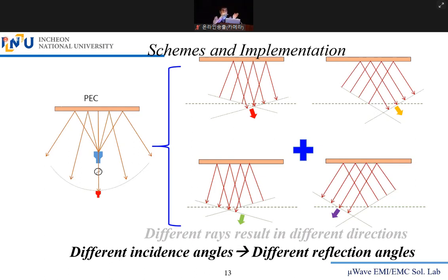These are called rays, R-A-Y-S, rays. So here, the rays are diverging, and with PEC, with no distortion, actually the angles of reflection are determined by electromagnetics. I told you, if you change PEC to dielectric material, plastic, wood, glass, the angles of reflection for these rays are the same.